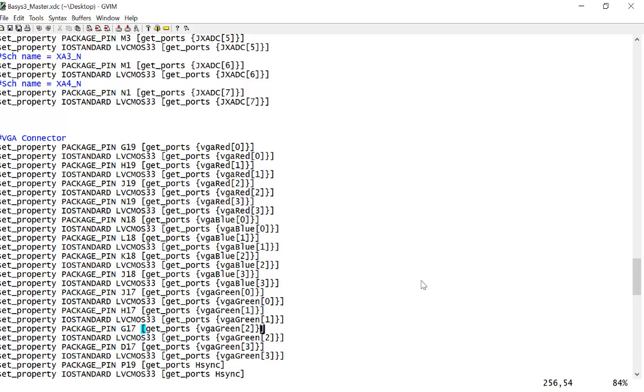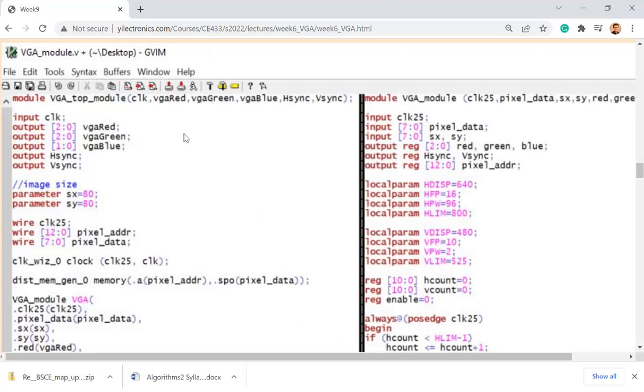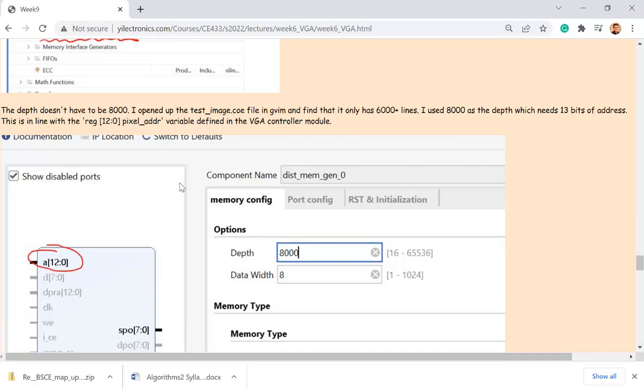So what's the consequence of reducing the number of bits for each color? So totally you can use 12 bits, right? But we are not using all the 12 bits. We only use 8 bits. Then we are doing like 3, 3, 2, right? 3 for red, 3 for green, 2 for blue. So which means that, you know, we're reducing the number of bits, which means it's not resolving all the color changes. So we're eventually getting some skew on the display. So that's when we're looking at the basis 3 picture over here.